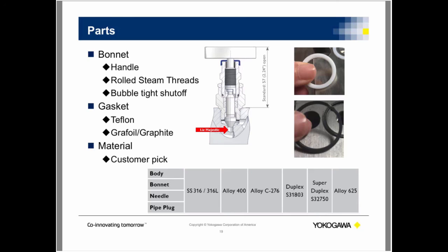With this Teflon, you have to make sure that you correctly torque to seal the transmitter to the manifold properly, because if you don't, you can cause a lot of stress on the Teflon, making the manifold capable of leaking. The one good thing about Teflon is it's easy to remove and replace. You're not having to fight it to get it out. Generally, they just pop right out and pop right back in. A lot of customers love a Teflon gasket.